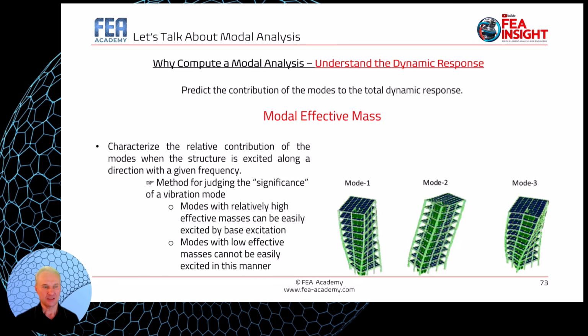Okay, so modes with relatively high effective masses can be easily excited by base excitations, and modes with low effective masses cannot be easily excited in this manner. So it's very important, before conducting a dynamic analysis, to have knowledge of that. Okay, how the mass will influence the response.